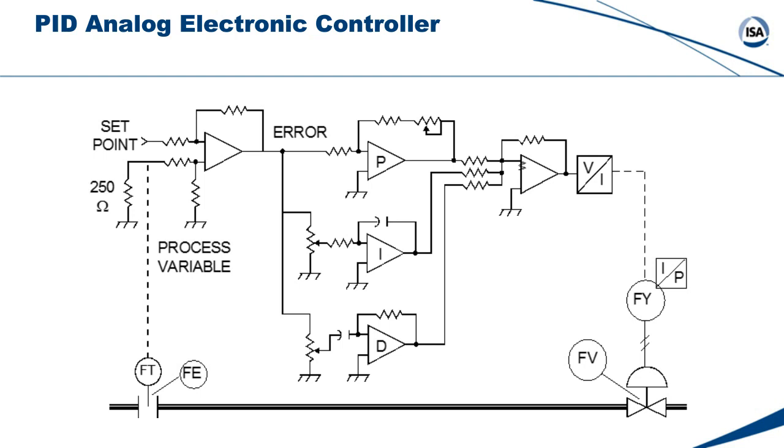Execution of the PID control algorithm in the controller should not be faster than the I/O update time, or the time it takes to update the inputs and outputs from the field. Otherwise, the PID algorithm will execute using stale or old input data.